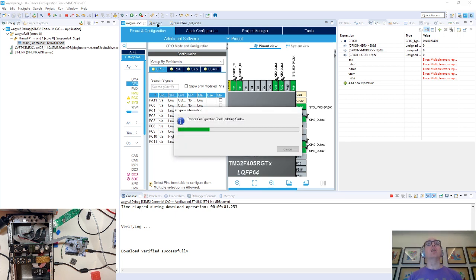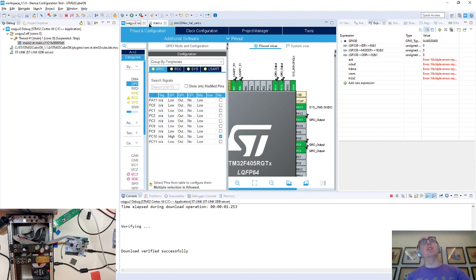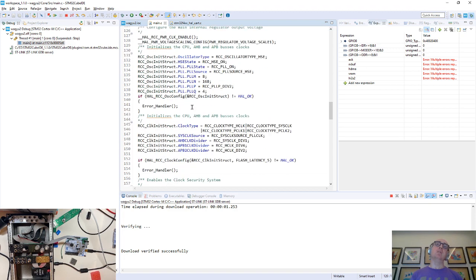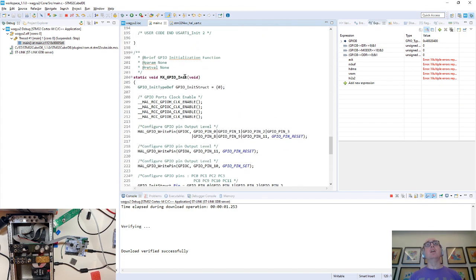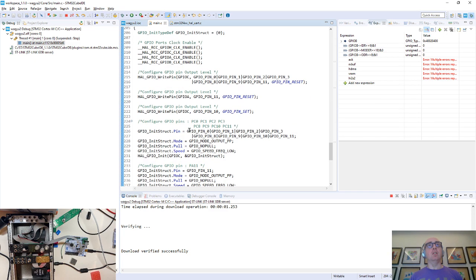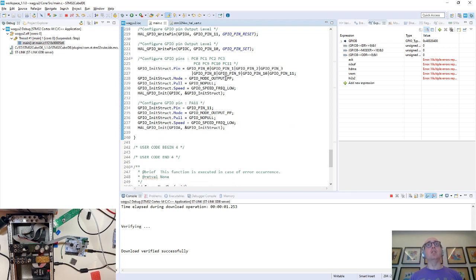It does code generation. Would it be instructive to look at the code it generates? It's pretty simple. Oh, the MFC point. Yes, it does feel a bit like MFC. And luckily, it's slightly nicer than MFC in my ancient memory. So they write routines like GPIO init, and then they basically set all the pins low. Classic sort of stuff. Set up the pins. Push pull means it's not open drain. It can pull it high or low. No pull ups. Low frequency, so it slews nice and slow, doesn't generate noise.